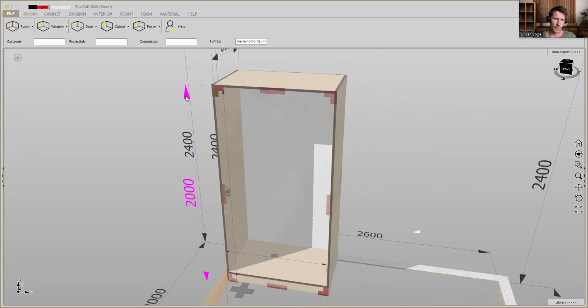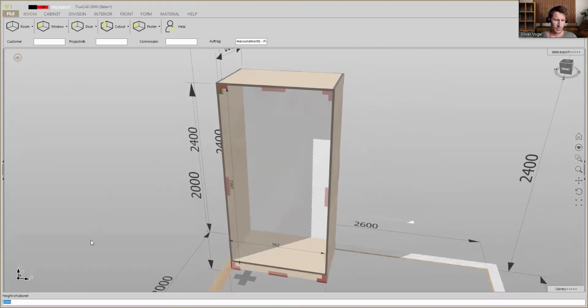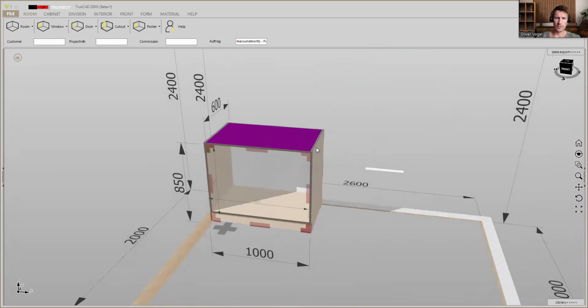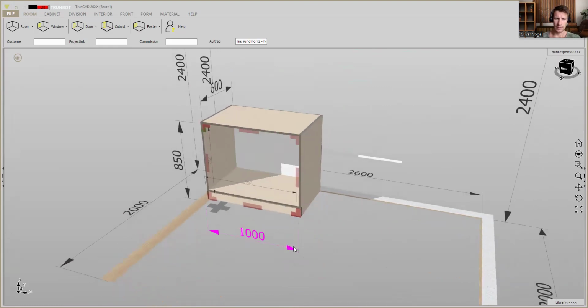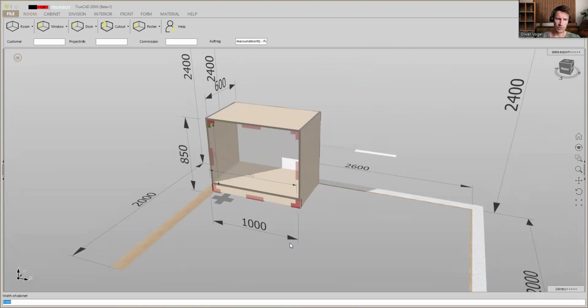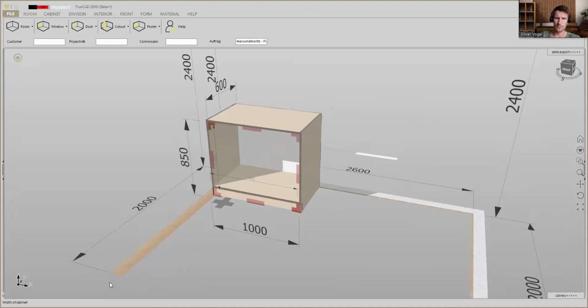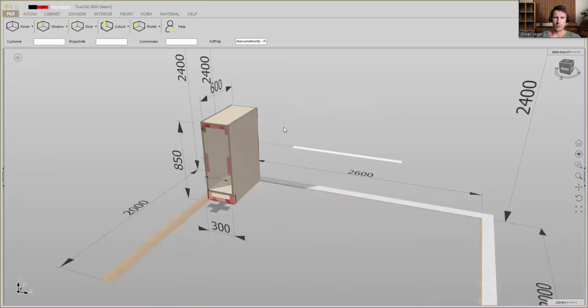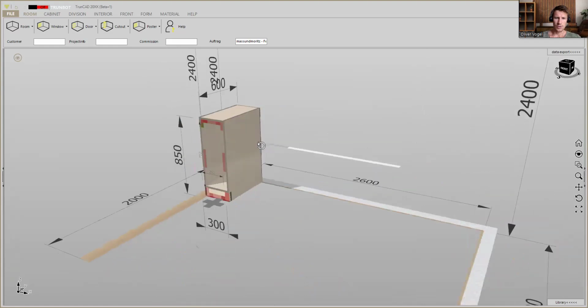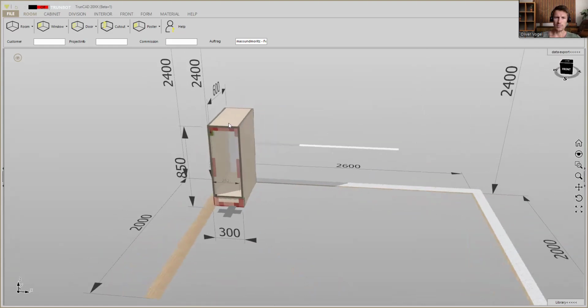The window on the bottom left corner opens, and here we type in 850, in millimeters, and confirm with enter. We do the same with the width of the cabinet: we click on the dimension, the window opens, and we type in 300. So that is our dimension.